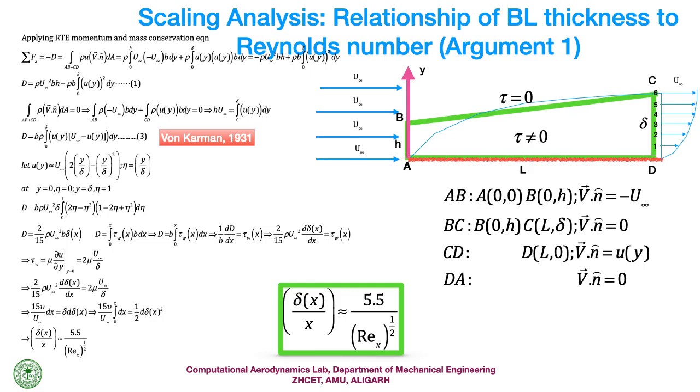And this is perpendicular, in the direction of the paper or the screen right now, that is the Z direction. It has a thickness b. Okay, the momentum equation is shown over there. You can see the maths which I have done. You can see from here that the drag force is the only force in the x direction, because shear stress is not zero at the surface AD.